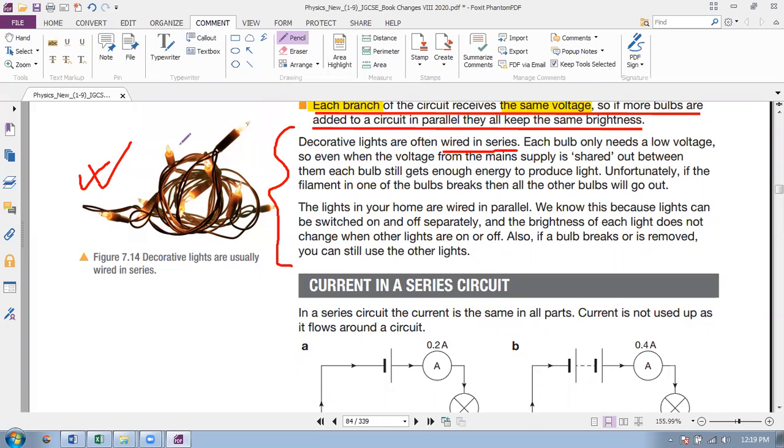But generally, electricity does not go through that wire because it has a bit higher resistance than the bulb. So current always follows the low resistance path, so it goes through the bulb naturally. If one bulb goes off in a decorative light, then current goes through that parallel high resistance path to the next.